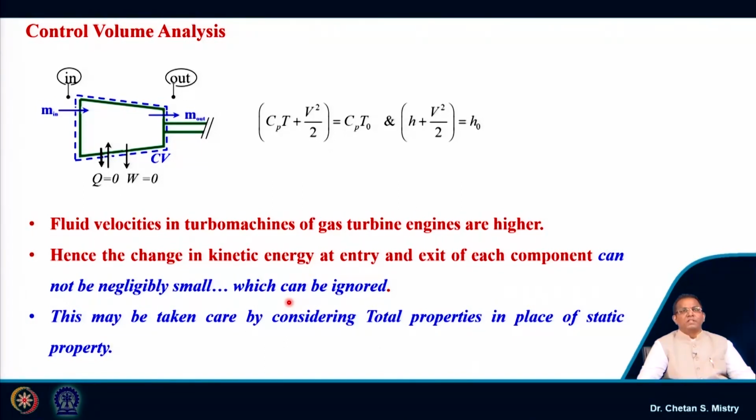This is always a confusion with a lot of literature available in the open domain. They use static properties, but when we are discussing aero engines, we need to be very careful, as we are more interested in total properties compared to static properties.